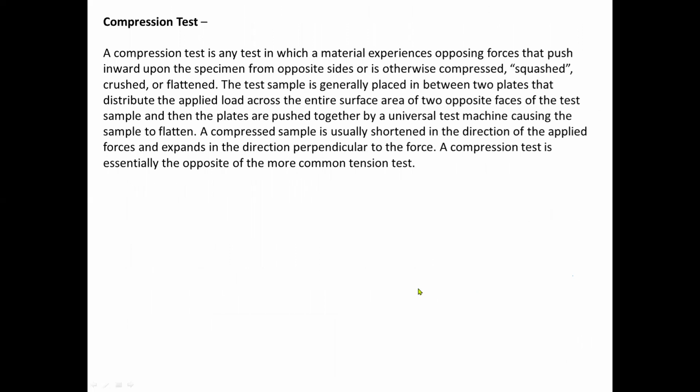We also have the compression test. It is any test in which a material experiences opposing forces that push inward upon the specimen from opposite sides or is otherwise compressed, squashed, crushed, or flattened. The test sample is generally placed between two plates that distribute the applied load across the entire surface area of two opposite faces of the test sample, and then the plates are pushed together by a universal testing machine, causing the sample to flatten.